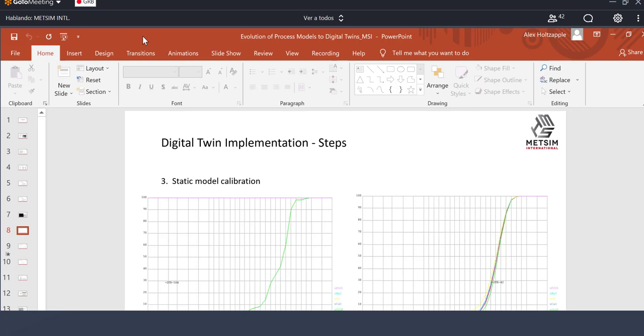So on the left, we have just the one stream in this case, because maybe they took the assay, they did the particle size distribution, but they didn't do any sort of chem scan analysis or detailed assay per screen size. Whereas we can see in the model on the right, we have multiple curves, each color-coded here based on the mineral. You can see on the right, we've got iron, magnesium, calcium, etc.